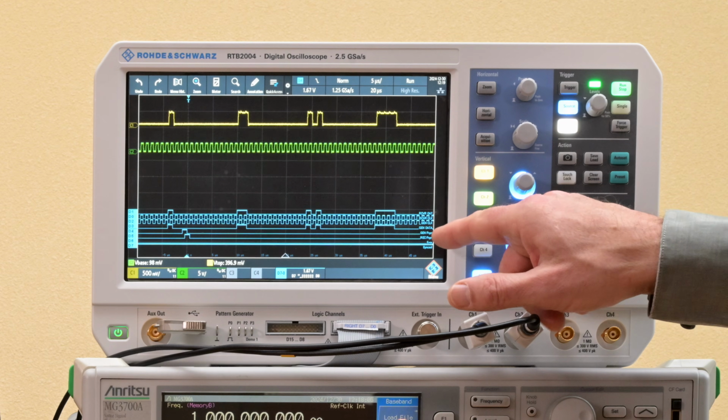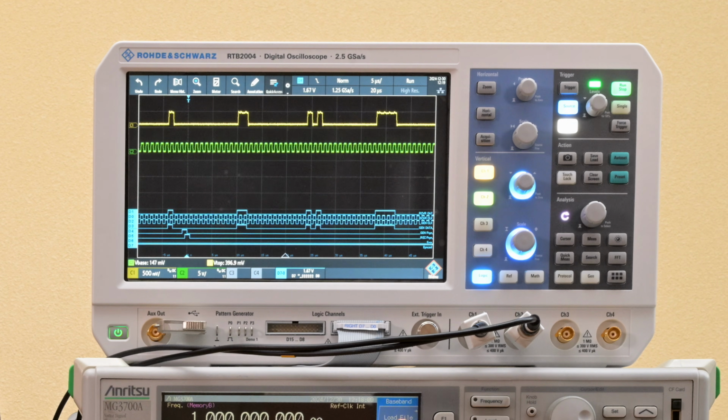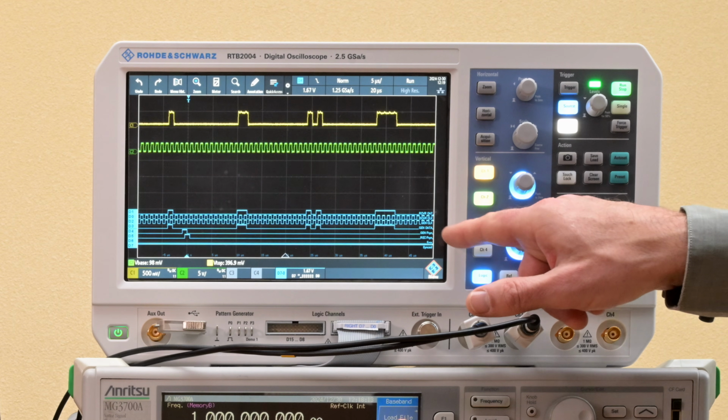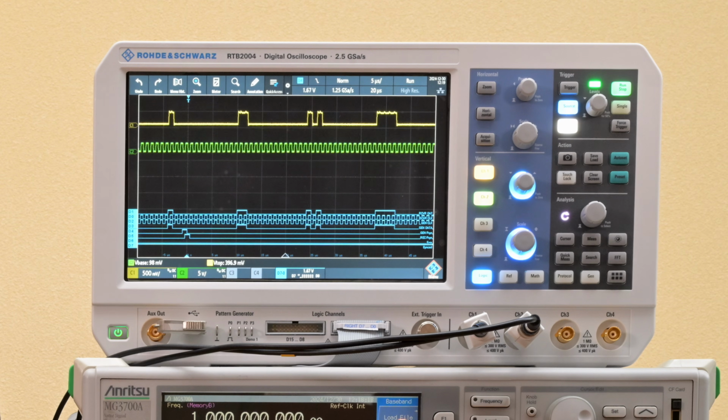We also got, and I write that a lot, a sync generator. So that indicates the start of the pseudo-random sequence, and we both got that on the receiver side and on the generator side, and you will see that the receiver side will lag a little bit in time before it actually regenerated that type of signal.